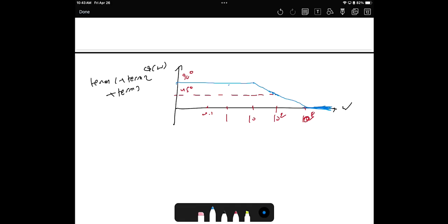Yes. What are the practical applications of designing a phase shift? Most likely you will use it in control systems. In control, there's a transfer function, and the zeros and poles really matter. Sometimes you need to move the poles. The poles determine whether the system is stable or unstable. We said bounded input, bounded output system.